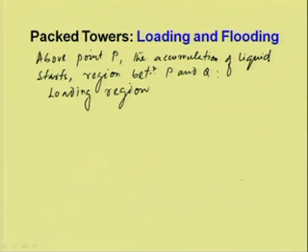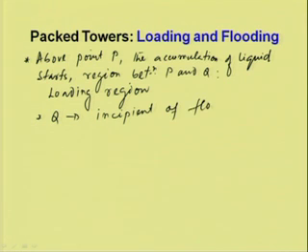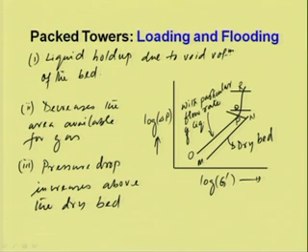And also the point Q is known as the incipient point of flooding. So, the flooding starts at point Q, where there is a sharp increase of pressure drop.